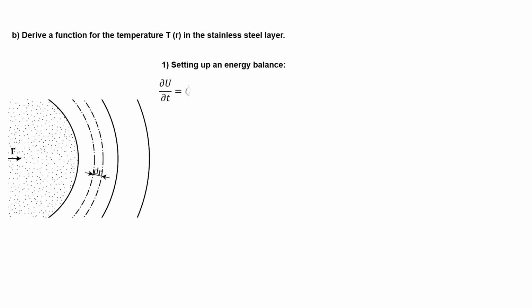So we know this general expression for an energy balance for a closed system without sources. First, we draw all fluxes. Some heat will be conducted towards our element, but at the same time, heat will be lost due to conduction as well, which are shown by these two fluxes. We're still dealing with a steady state system, so everything differentiated with respect to time will cancel out, which gives us the following energy balance. Now we have our balance and we should start to define all the elements.